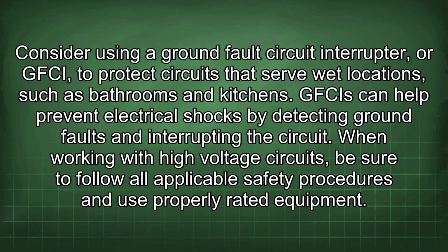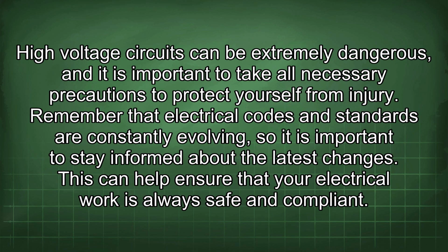Consider using a ground fault circuit interrupter, or GFCI, to protect circuits that serve wet locations such as bathrooms and kitchens. GFCIs can help prevent electrical shocks by detecting ground faults and interrupting the circuit. When working with high voltage circuits, be sure to follow all applicable safety procedures and use properly rated equipment. High voltage circuits can be extremely dangerous, and it is important to take all necessary precautions to protect yourself from